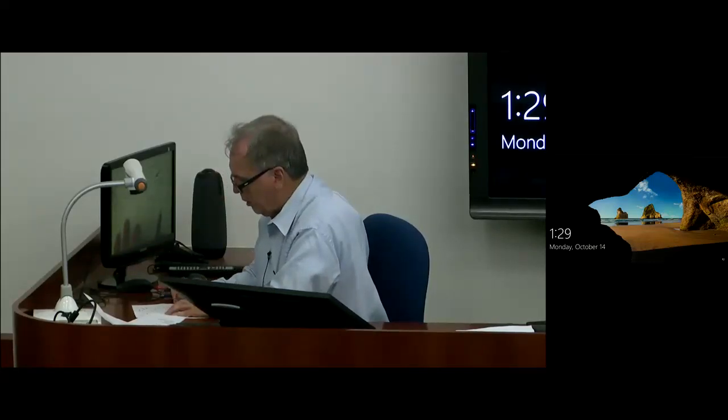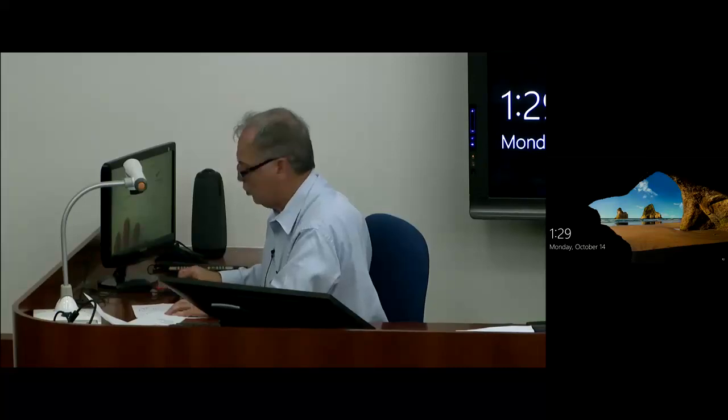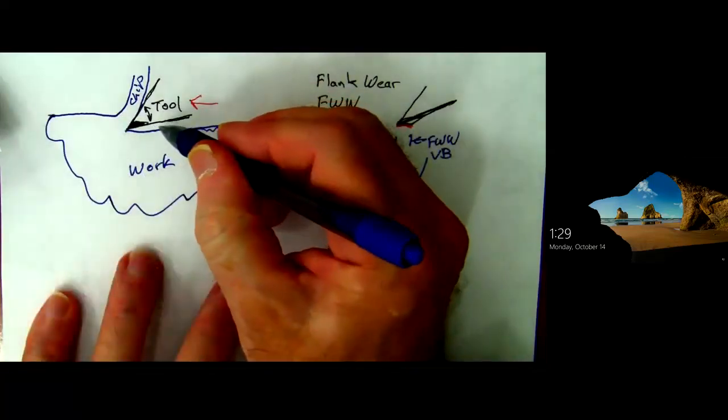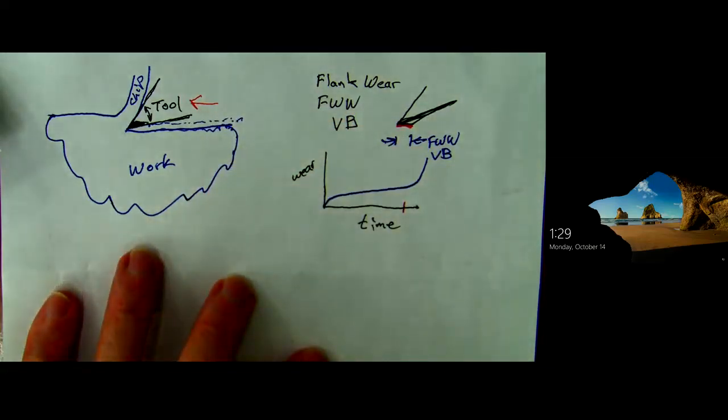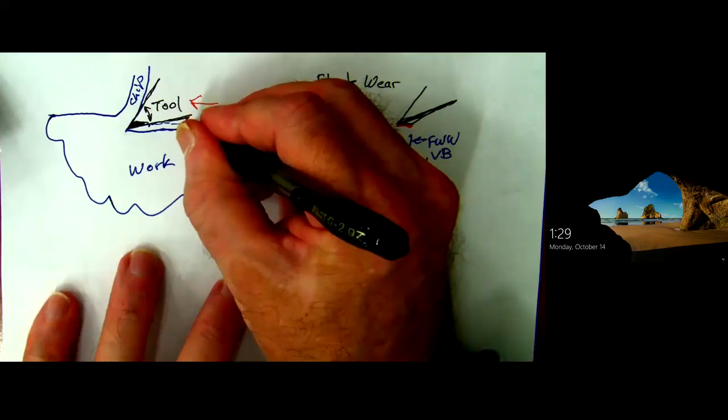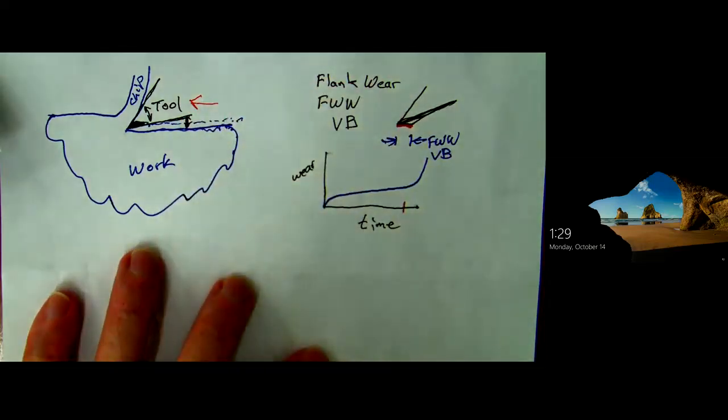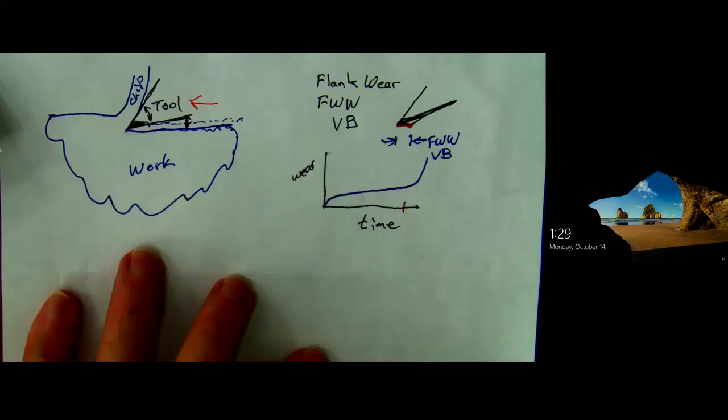Okay, one thing that can also happen is you lose tolerance. So you got to stay on top of this, because now the top surface will be up here, and you might lose tolerance a little. Now, in general, that angle is really shallow. The clearance angle in here, we're usually talking single-digit degrees. 5, 6, 9, something like that. Very, very shallow in there. So it'll take a long time before that wear really causes you to lose tolerance, but something to think about.